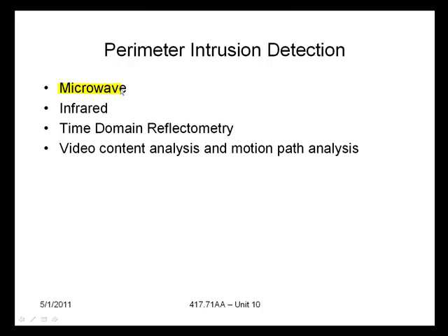Monostatic microwave sensors may feature a cutoff circuit, which allows the sensor to be tuned to cover only the area within a region. This helps to reduce nuisance alarms. The fact that microwaves may extend beyond the area you're protecting means that they may respond to motion outside the area that you care about and result in false positives.